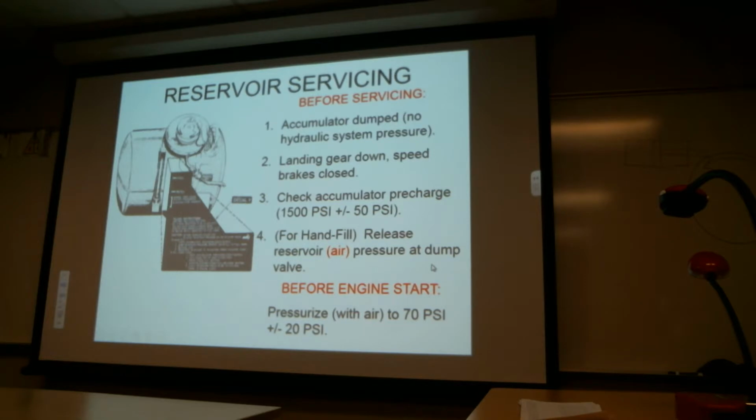This is important to prevent cavitation of the pump. If you don't do this, you're going to possibly cavitate the pump, which is very damaging to the pump. You already saw the video. And also there's no lubrication going to the pump, because the hydraulic fluid provides the internal lubrication necessary to prevent it from burning itself up. They might have a pressurization valve that allows you to use a little bit of shop air. They do on Beechcraft aircraft. So if you've serviced the reservoir, one method of putting the air pressure back in the reservoir before you start is to use air pressure from shop air.